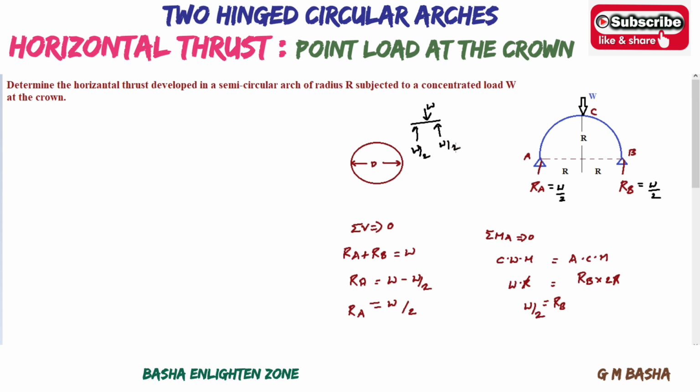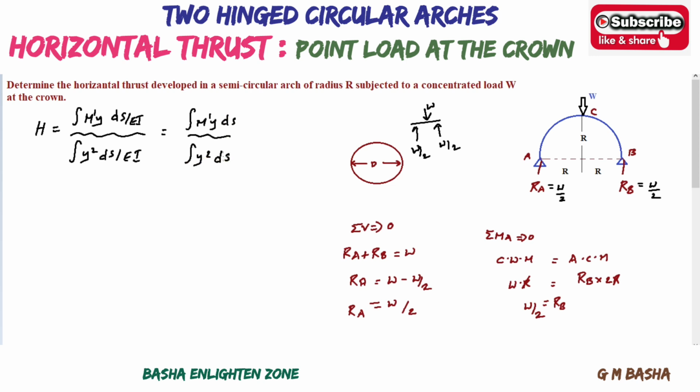For example, if a UDL is acting, you will get WL by 2. Here it will be in terms of R: W into 2R by 2 means you will get W into R. I will explain that while solving the example based on the UDL. After knowing this, we know the formula: horizontal thrust equals integral of M dash y ds by EI, and the denominator is integral of y square ds by EI. Here EI is constant in both, therefore you get directly integral of M dash y ds by integral of y square ds.